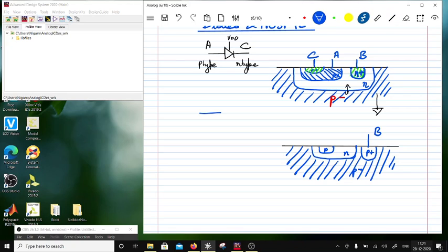You have an anode, which is a p-type side, and then you have a cathode, and then you have a body terminal which will be connected to ground. So in this case the body terminal would be connected to ground, and now this whole substrate is grounded, and you can make these contacts. These are called substrate contacts. You are going to make these contacts all around the device, right? And then you have got this as anode, this as cathode. So this is going to be your device which is sitting outside the well, right?